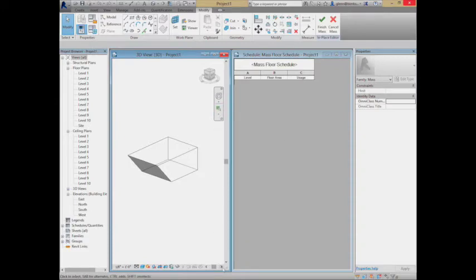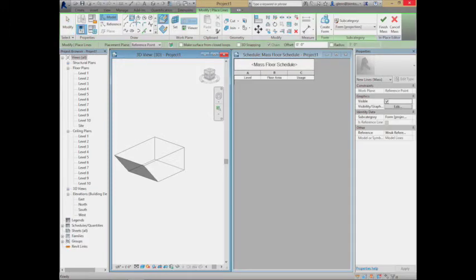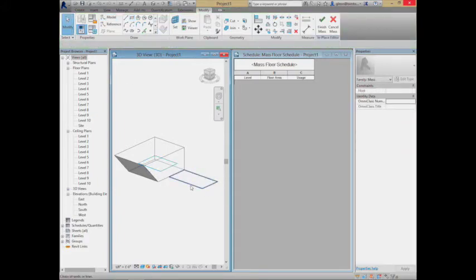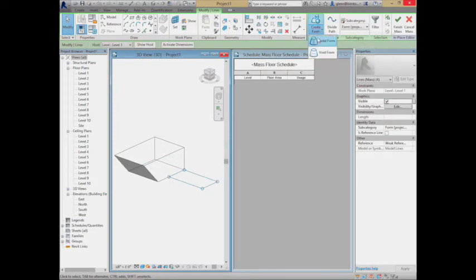We can also start adding to our building. For example, this building right now is sort of a single block. If we wanted to have an L or an extension to it, I could draw some more forms. I could draw this either on level 1 or extrude it out from the side of the building. It doesn't really matter which way. Anything that you enclose as a form will ultimately be divided into floors. So let me draw another little extension to the building over here. Now, this is just a profile so far, so I need to do the same thing in terms of creating a form.